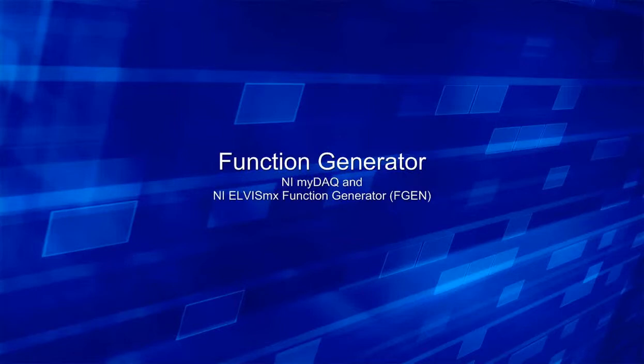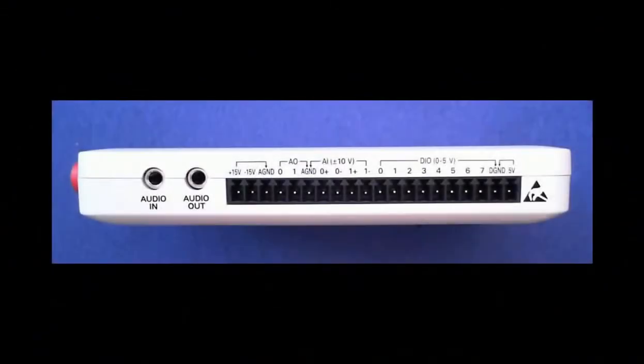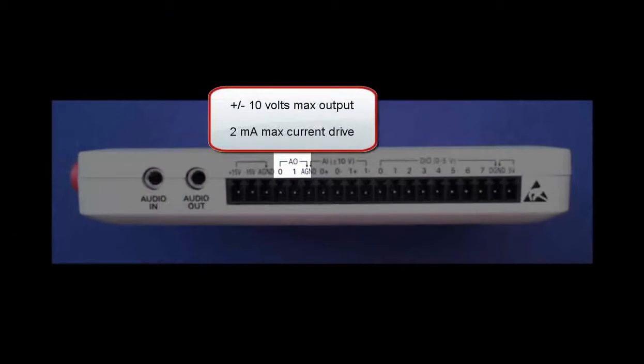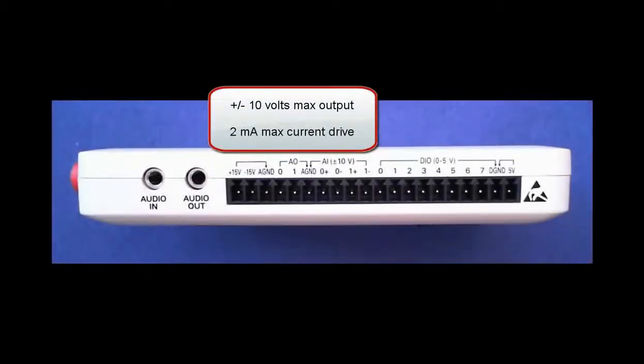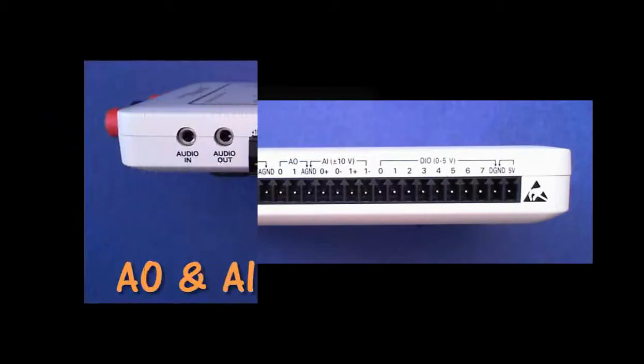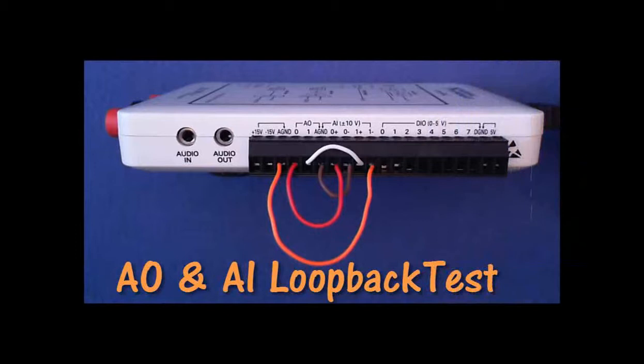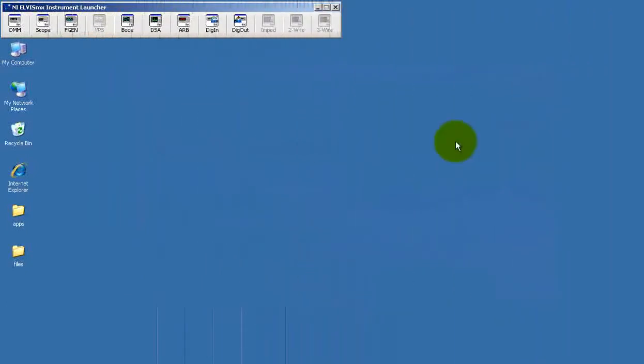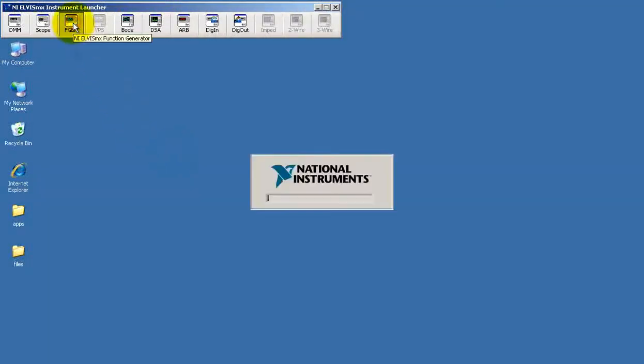Let's learn how to use the function generator on the NI myDAQ. As we're getting started here, we'll be concentrating our attention on analog output 0. It's important to remember that this is limited to plus and minus 10 volts maximum output voltage and 2 milliamps for maximum current drive. I'm using the loopback connections here so I can watch the analog outputs on the analog inputs. We'll be using the oscilloscope to confirm the operation of the function generator.